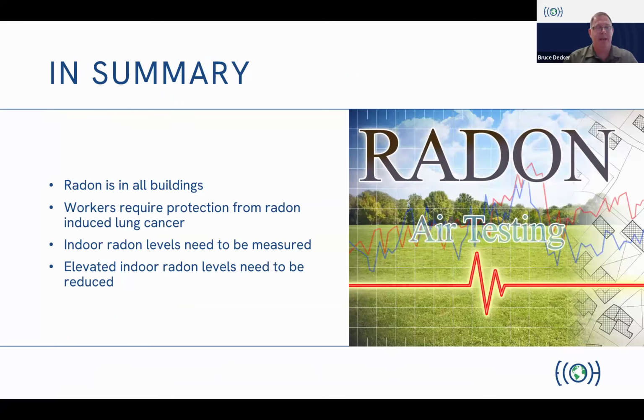Okay, so in summary, radon is in all buildings. You don't know how much unless you test. Workers require protection from radiation and radon-induced lung cancer. Indoor levels of radon need to be measured to know what's there, and elevated levels need to be reduced, or you need to control that worker exposure somehow.